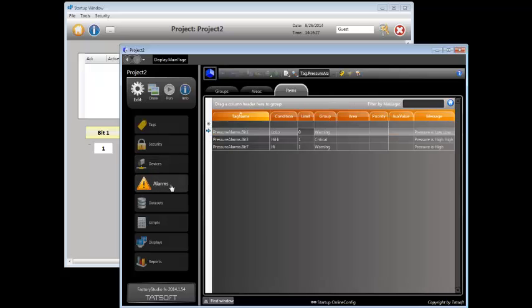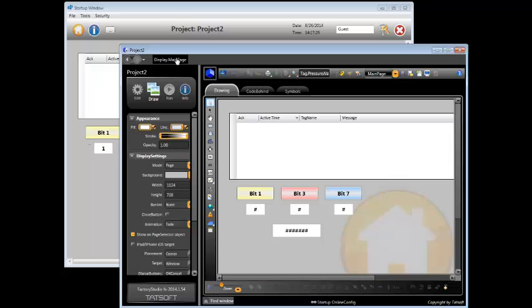Next, we define the alarms. To access the bits of it, you simply follow the name of the tag with the designation of the bit you want to use. In this case, we have 3 alarms defined from the pressure alarms address: bit 1, bit 3, and bit 7 for low low, high high, and high conditions. In this example, we created a display to use the alarm view control to list active alarms, show the values of the individual bits, and created buttons to toggle their values.